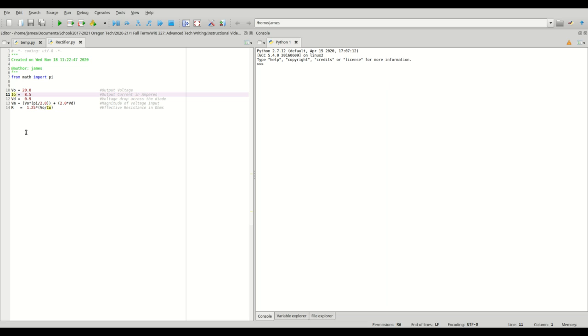In my version of LTspice, I've estimated the voltage drop across the diode to be about 0.9 volts. Trust me, that number will be important later. Find what it is on your LTspice and write it down. The other super important variable is the magnitude of the input AC voltage waveform. You can calculate that from the output voltage. Vm equals VO times pi over 2. You can rewind to my notes and sketches if you're unsure where that comes from.